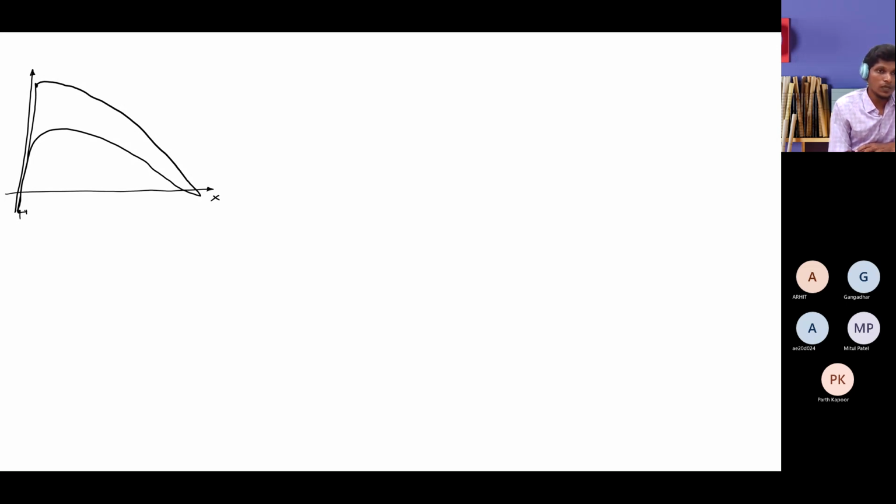If there is a presence of high pressure gradient regions, there are more chances of seeing flow separation. This is the negative value and this is the positive value. This is the pressure coefficient, we say. Okay. And the pressure coefficient can be linked from our previous understanding with respect to Bernoulli. We derived that the pressure coefficient is 1 minus U by U infinity squared. Okay. And now let's go to different kinds of series in the airfoils.